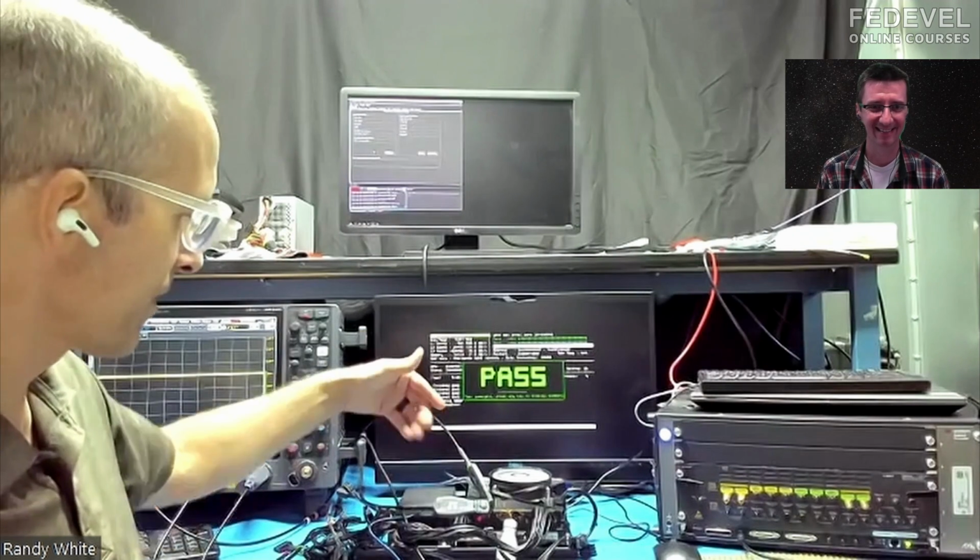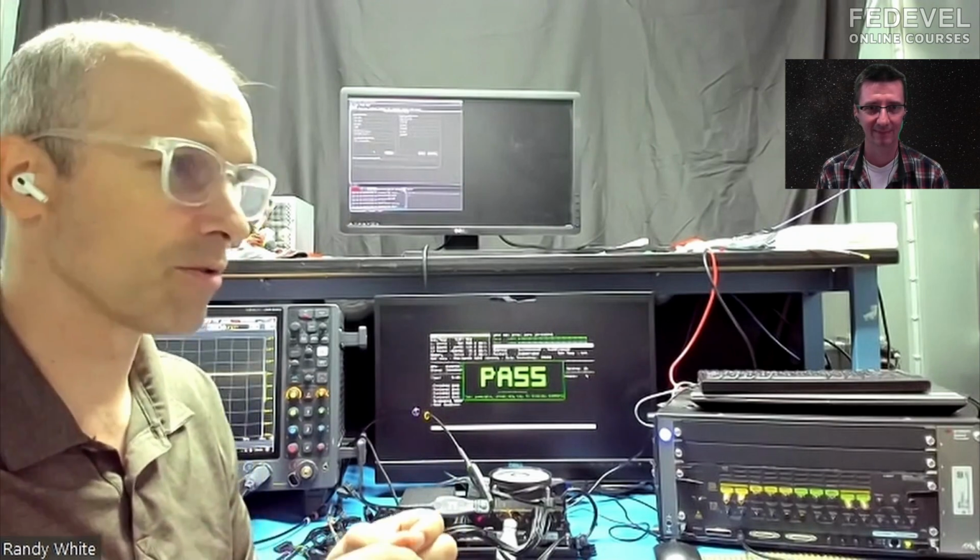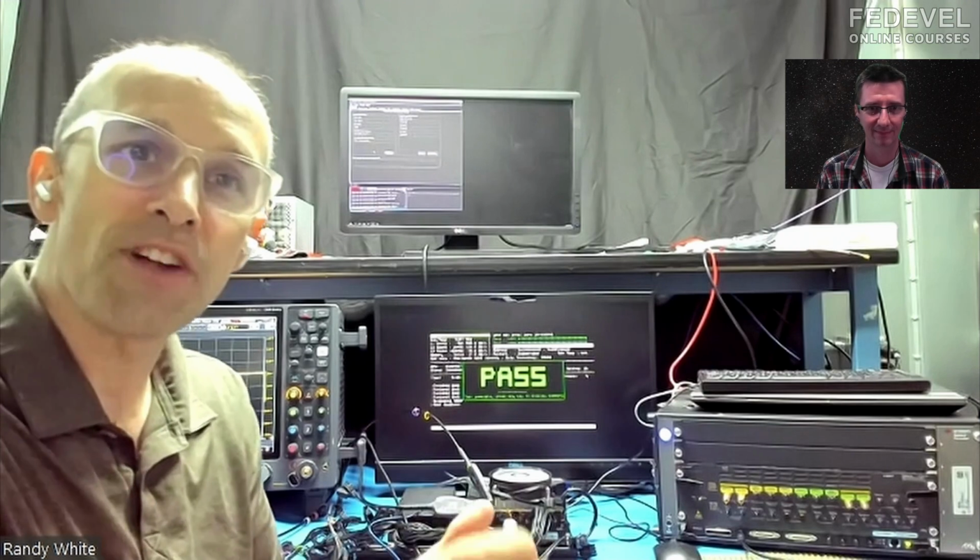We have 3 probes connected. These are soldering probes. So you have to be able to get access to the signals of interest, solder them in, and my eyes are not good enough, even though I got really strong glasses. Now you have to have a microscope. The pitch is really small. So you solder them in, and then that allows you to observe the signals that are going back and forth between the processor and memory.